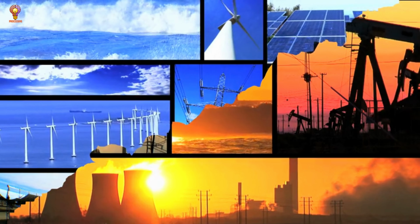Supercritical and ultra-supercritical coal plants operate at higher temperatures, over 600 degrees Celsius, and pressure above 22.1 MPa, improving efficiency. Ultra-supercritical plants can achieve 45 to 50% efficiency, compared to 33 to 38% for conventional coal plants. This reduces coal consumption and CO2 emissions per unit of electricity. Integrated gasification combined cycle (IGCC) converts coal into syngas, a mixture of hydrogen and carbon monoxide, before burning it in a gas turbine.